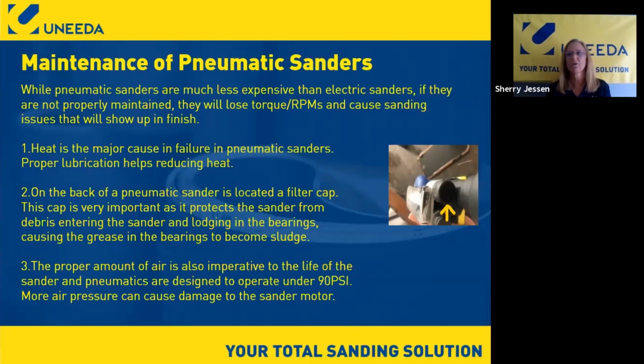If you don't lubricate the sanders, and I've had people say they were told they really didn't need to lubricate it, you need to lubricate your sanders. You've got metal parts, and you've got the phenolic vanes in there. As they come out, they're running against that plastic housing. Without lubrication, that's friction, and all you're doing is eating away at that housing.